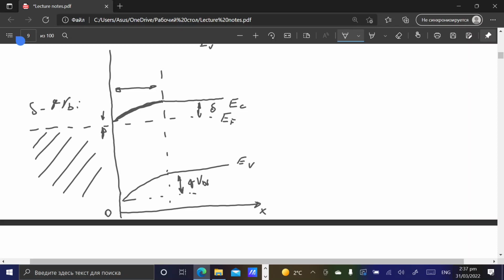That results in this nice linear current-voltage characteristic, which satisfies the requirements for an ohmic contact, whose purpose is only to collect charge carriers from inside the semiconductor and put them into the external circuit, or the opposite, to inject them from the external circuit into the semiconductor device stack.